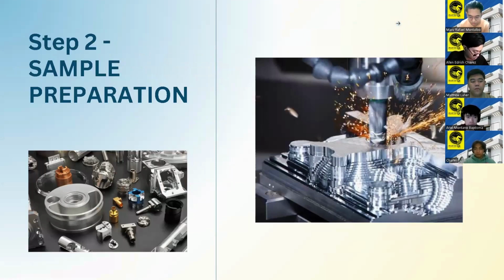The next step is sample preparation. Prepare the selected specimens by cutting, machining, or otherwise modifying them to the required size and shape for testing. Ensure that the preparation process does not introduce any defects or alter the material's property significantly.